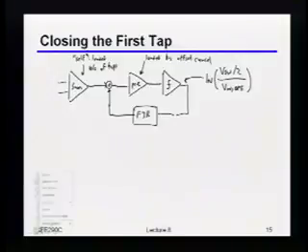So in other words, if I have some peak swing at the output, then whatever that peak swing is, I have to at least get, okay, nominally eventually I have to get it to full rail, but maybe from a digital delay standpoint I only have to go half of the way, right? But the amount of time it's going to take me to do that regeneration is going to be at least this, right? In other words, it's going to be just some minimum amount of time it takes you just to get that small signal back up to the large enough rails.